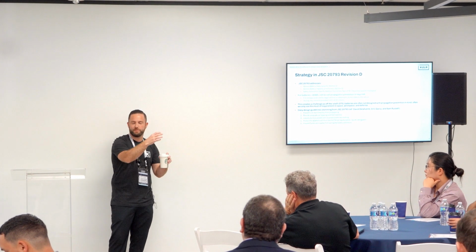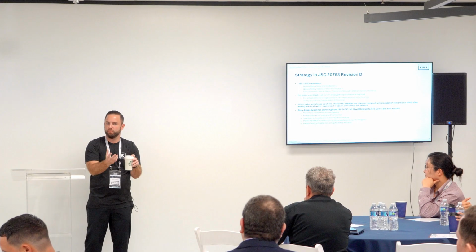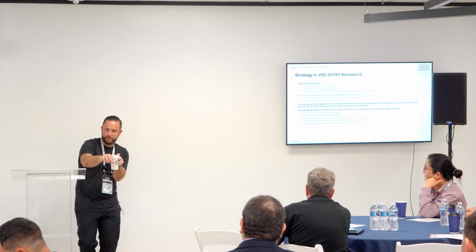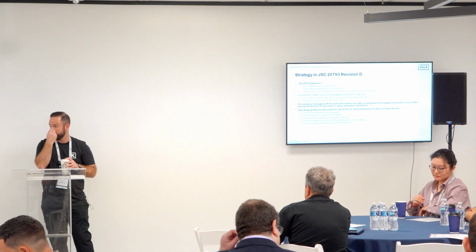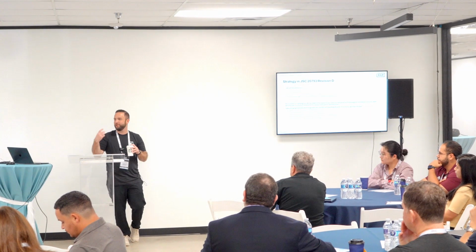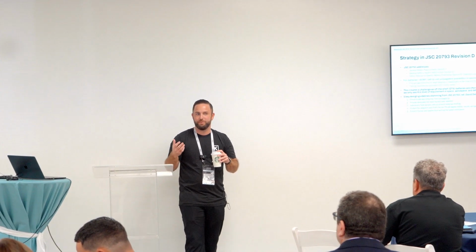And when you start talking about small sat, CubeSat, secondary payload batteries, people are used to working with these innately lightweight, small batteries that are just going to fit in this little nook and cranny of their spacecraft, to now having requirements that we have to satisfy, like 20793, where all of a sudden it's like, gee whiz, I got to have a housing now for my battery because I got to do ejecta management. I got to have flame arrestor because I can't have any fire going off. I got to do all this abuse testing, right? It creates challenges.